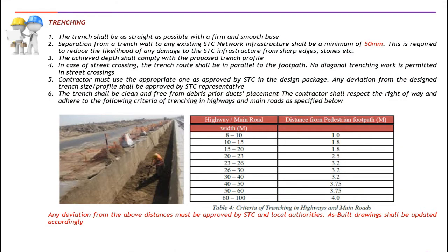Okay, trenching. This implementation technique is the most preferred method for the deployment of telecom infrastructure, as it offers faster performance compared to other trenching deployment methods. As we said earlier, before starting any civil works like trenching, you need to have a look around the route to make sure that you can deliver the work and that everything is free from any obstruction that may hamper your implementation later on. Then do some ground scanning as well to prevent any damage to existing underground utilities.